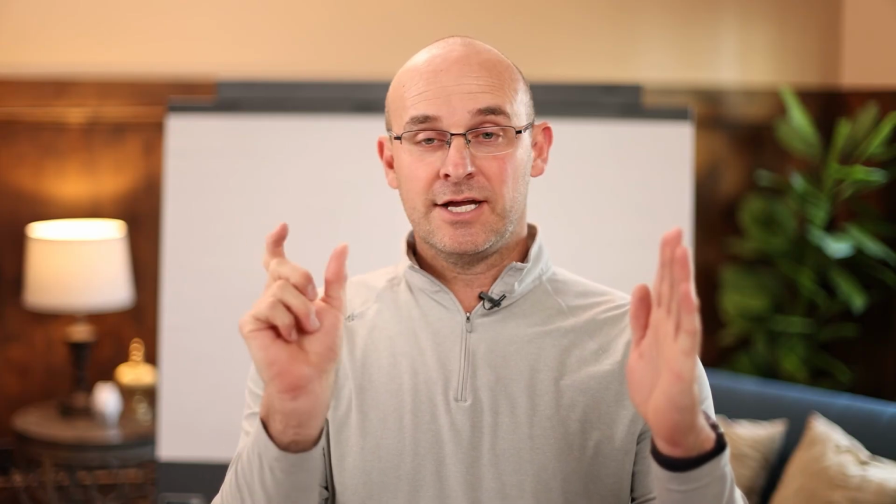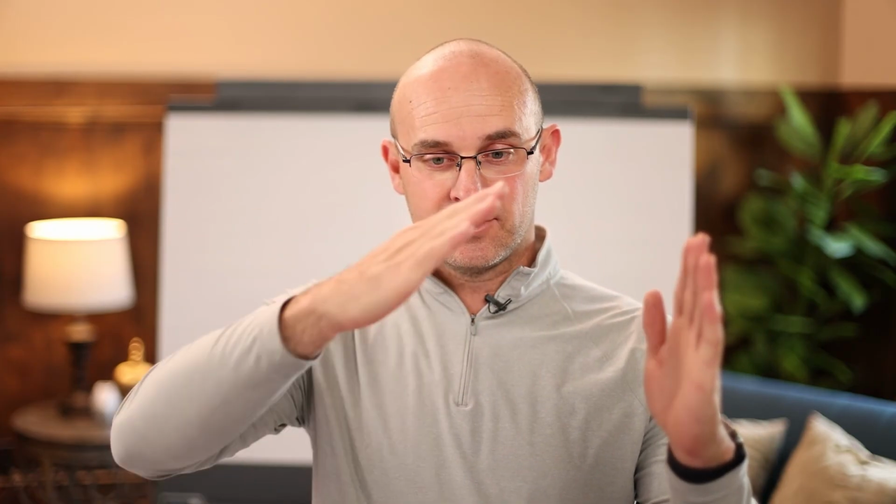And so one last bit of advice that I want to give you is make sure when you absorb a delay, if you haven't heard anything else, I want you to hear this. Here's your construction schedule. Again, you have to have buffers, you have to see it, and you have to delay it properly, but you will not target a proper end date or overall total project duration unless throughout the schedule you have that trade flow, meaning every trade is flowing from area to area to area, and it's never stacked. And so whatever conversation you have with your owner, make sure that your overall duration and your critical path is correct by having that trade flow.